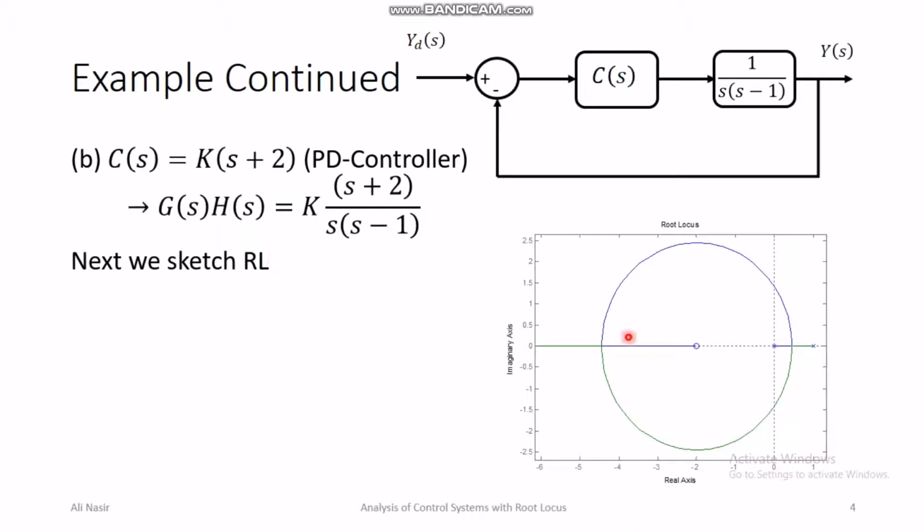And now you can see that these two poles, the pole at 0 and the pole at +1, once again travel towards each other, break away and enter the open left half plane. But this time, since we have added a zero and no pole, the difference between poles and zeros is 1 and no longer 2. So these poles do come back and break into the real axis, and one of the poles travels towards the zero and the other one goes as an asymptote to infinity.